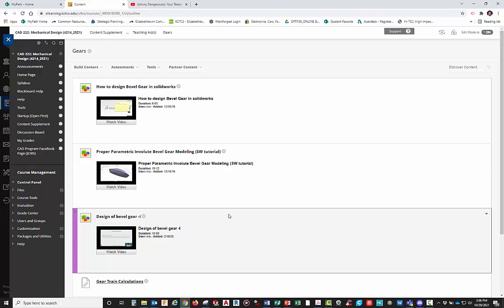AutoCAD Mechanical has some tools in it that you can use, I believe it's called the shaft generator, and you can actually create geometry for gears and other things that may help you. We used to take those before SolidWorks and Inventor had their gear generating tools, and we would make the gear outlines and then copy and paste it into our sketches and extrude it in SolidWorks or Inventor.